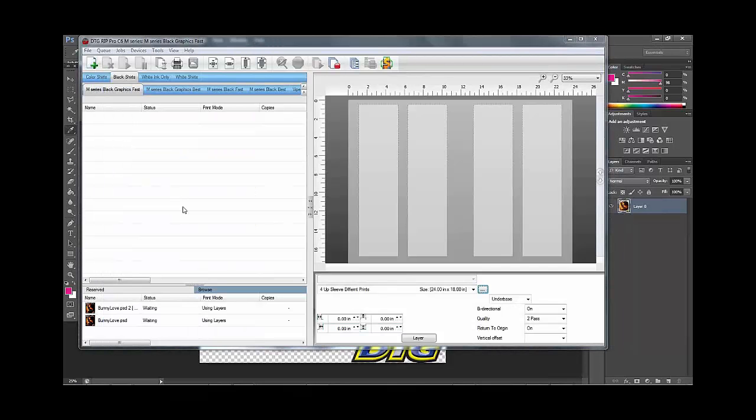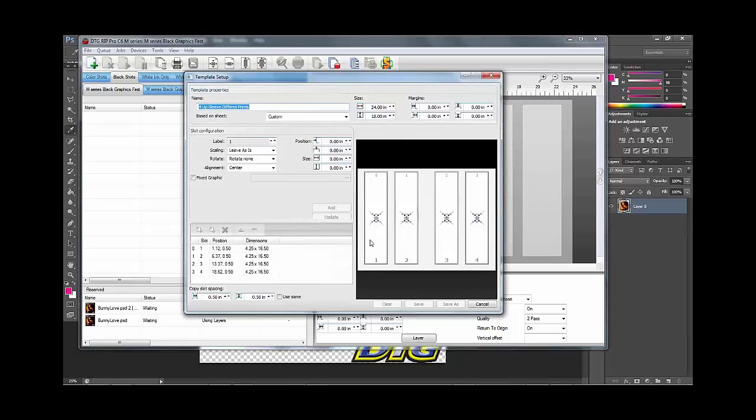The second part of your question dealt with centering on the platens. That, again, is what I want to do more of, showing people the template editor and using the template editor. The reason being, every single machine seems to have a little bit of variance. If your machine's off by a quarter of an inch or it's off by an eighth of an inch, it's always going to be that way. And if it's off by an eighth of an inch to the right, then I need to just push the platen over a quarter of an inch to the left. Yeah, that's good. Then that's where I can come in here and select that, bring that down just a little bit, and update and move all of those over just a little bit to compensate for that. Once I save that, it's going to be that way now, and I'm not going to have to worry about that anymore, because this is dead center regardless in the RipPro's eyes. So it's all really a question of whether that platen is truly underneath that portion of the print area.